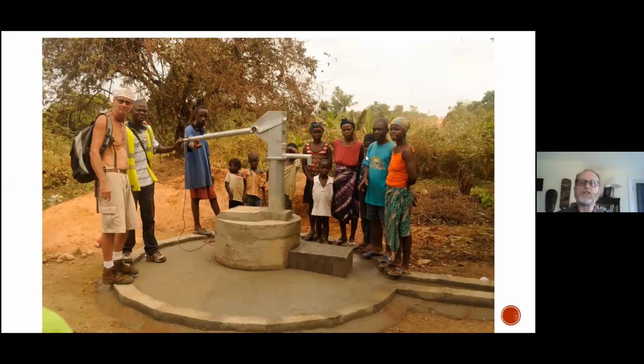A more advanced and very common, you might have wells like this. In fact, if you've seen them, let me know on chat. It's called an Africa Dev, so Africa Development well. And you can see it's basically 3 parts. Sometimes they're drilled, but sometimes they're hand dug and lined with concrete, like manhole sections that you would see in the sewer department. And then a slab around that allows for splash.